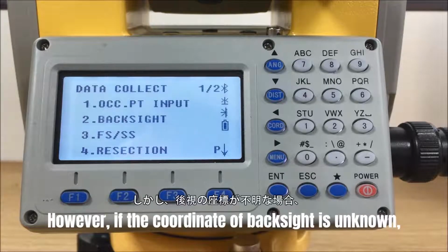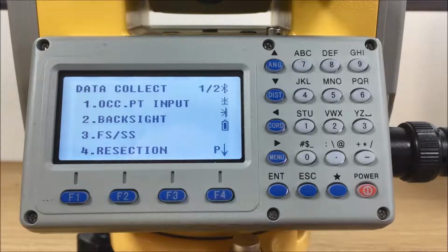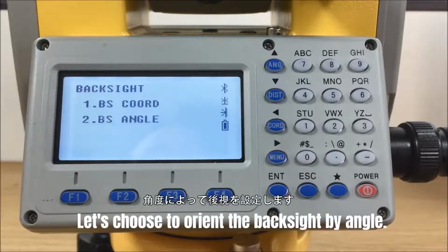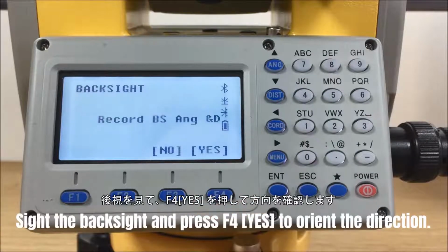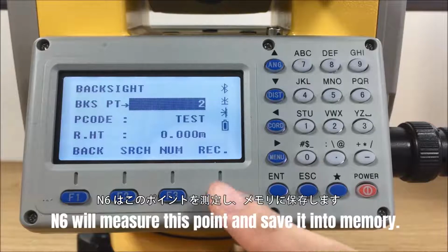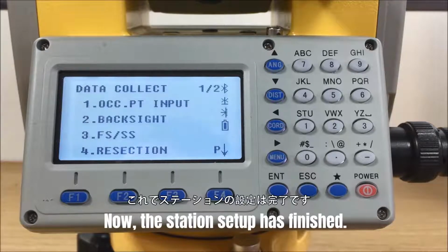However, if the coordinate of backsite is unknown, how can we orient the backsite? Click the second item. Let's choose to orient the backsite by angle, like 45 degrees. Sight the backsite and press F4 yes to orient the direction. N6 will measure this point and save it into memory. Now, the station setup has finished.